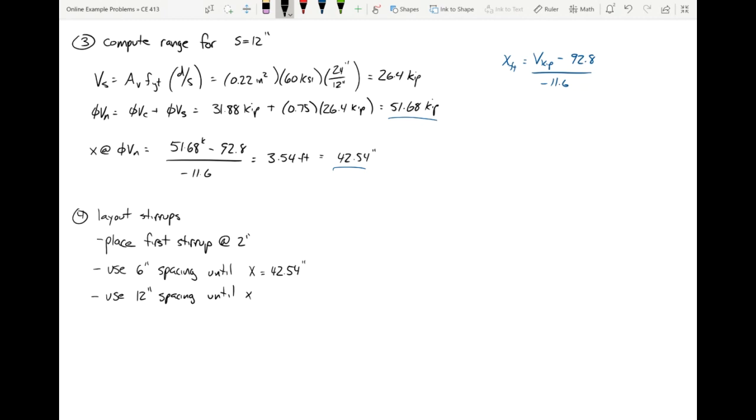And the end is going to be 79.51 inches. And that's because that's where X is at. This is the X value at half of PVC. So if you want, you can say this is X at half of PVC. This is the X from step 3, if you want to sort of flow chart that out.